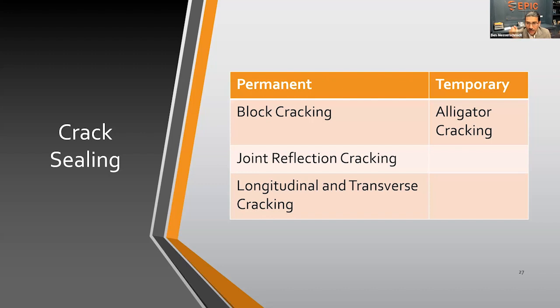Now, in alligator cracking, for example, the area may extend farther and will actually breach through any sort of seal coat that you have installed there, just because it's a bit more dynamic. And that was a structural based failure with the alligator cracking as opposed to the non-structural items that we have going on the permanent side of things. So it's important to know what available options you have when undertaking or thinking about undertaking a repair project to your pavement.